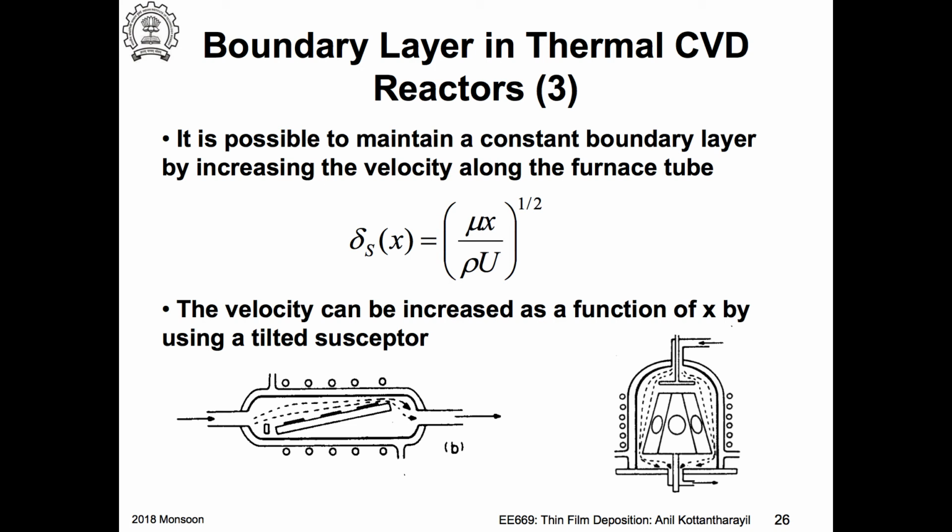At the farther end of the furnace, the thickness is much more than at the beginning. So the reactants take more time to diffuse through towards the end of the furnace. So the flux will come down, and as a consequence I would get a slower deposition towards the farther end of the furnace, if the transport through the boundary layer is the limiting parameter.